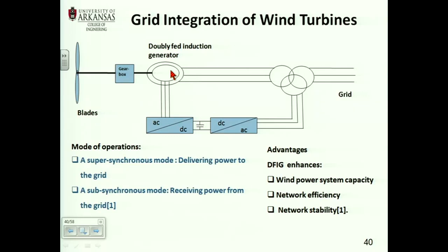But by controlling the electronics, you can change the resistance of the rotor. I don't know if in energy systems you look in detail at a wound-rotor induction motor, but that's basically what's happening. And so that allows you to increase the operating range of the wind turbine compared to the induction generator.